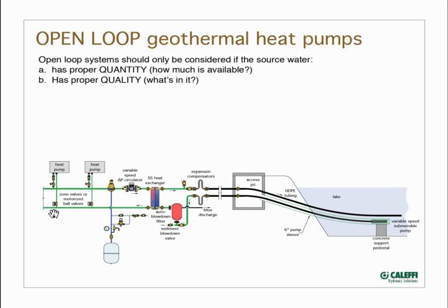Beyond that, over to the left, we've got multiple heat pumps. In this case, each one of them has a zone valve or a motorized ball valve that would open when that heat pump is operating. And we're combining that with a variable speed pressure regulated circulator. And that combination, some of you I'm sure will recognize, that's really the same thing we do with many hydronic systems for zoning. We use valves that open and close and a variable speed pressure regulated circulator. And this is what I mean about leveraging the state-of-the-art hydronics in combination with the thermal efficiency of the heat pump. So that's one way you could do it.